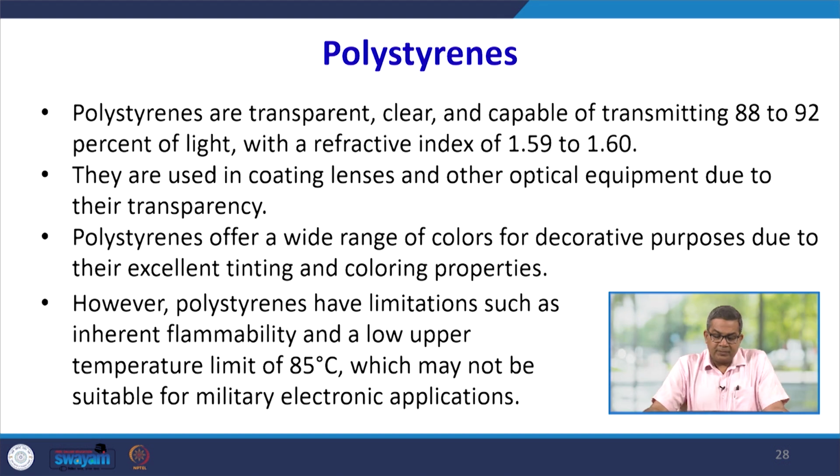Now, they are transparent, clear, capable of transmitting a large amount of light, and have good refractive index properties, and they are used in coating lenses and other optical equipment due to their transparency. They also offer a very wide range of colors for decorative purposes due to their excellent tinting and coloring properties. But simultaneously, they have some limitations like inherent flammability and an upper temperature limit of say 85 degrees Celsius, which may not be suitable for various specific electronic applications.